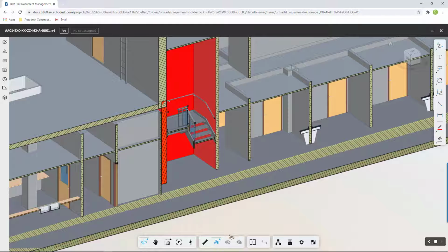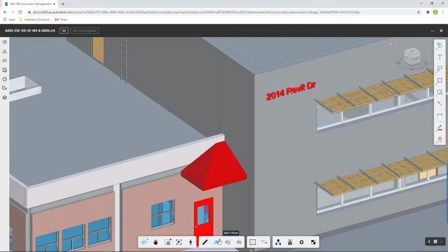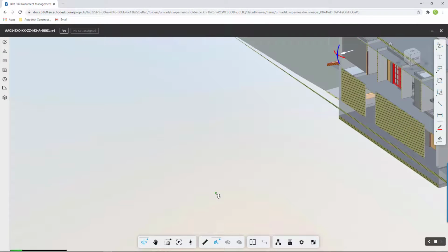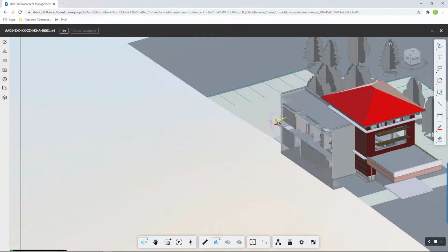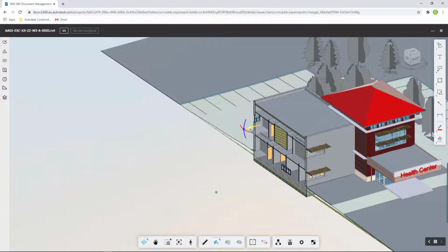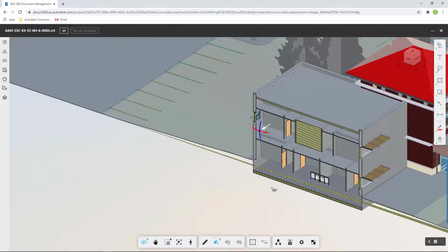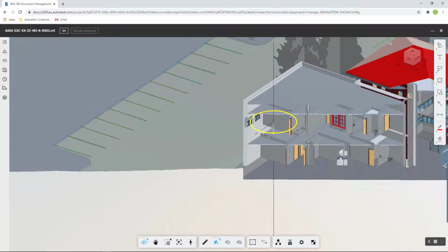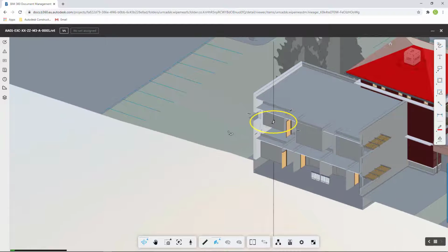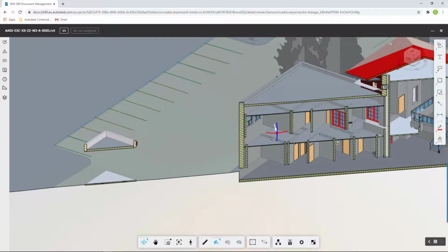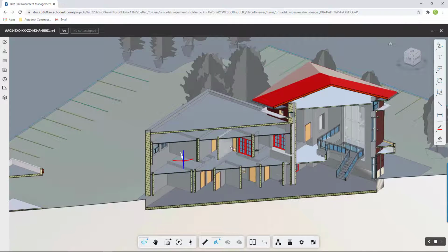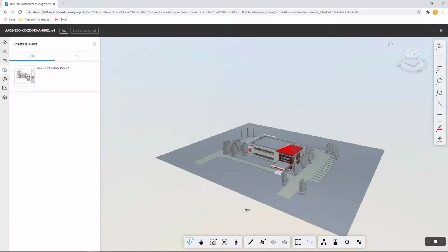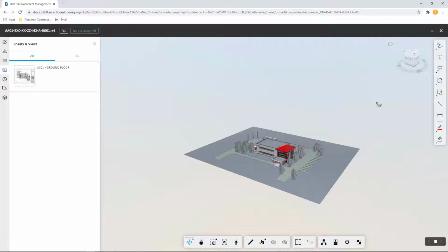By selecting the section analysis tool again, we can change the orientation of that plane. Selecting the flyout, we can now switch it to an X-plane. Again, we can use the gizmo control to slide this along the building. Whilst utilising the gizmo, we can also hover over and change the orientation angle of that particular section cut. It's important to note that the section analysis tools applied in the viewer do not reflect changes back in the Revit model.